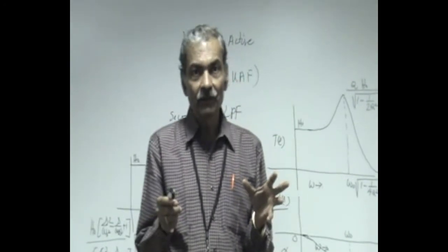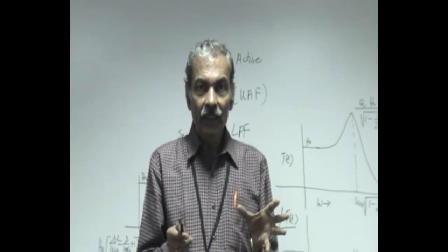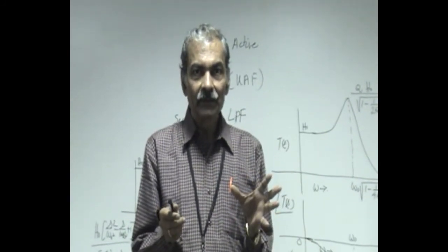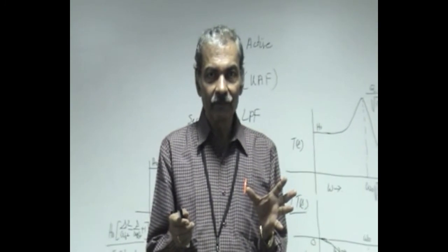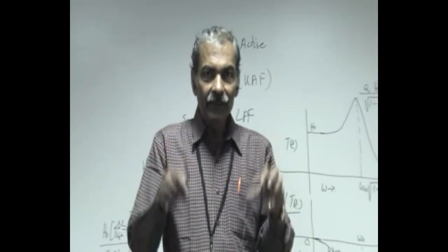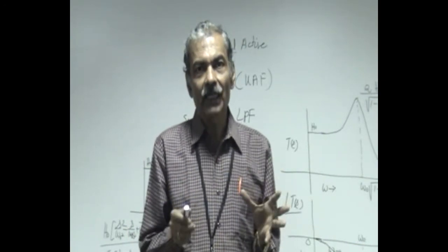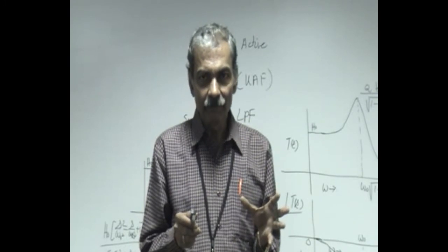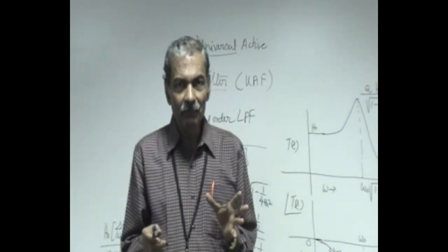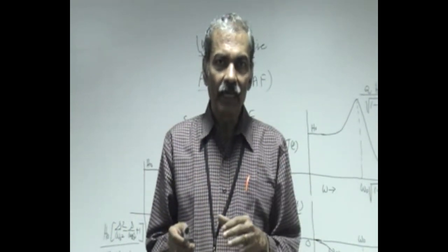Apply a square wave around the natural frequency of the system and see that the notch filter output is nothing but the harmonics of the square wave, and the band pass filter output is nothing but the fundamental. Therefore, this system can also be used as a spectrum analyzer for a periodic waveform, where the fundamental is picked up at the band pass filter output, and the rest of the harmonics occur at the band stop filter output.